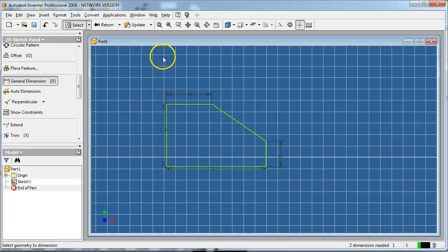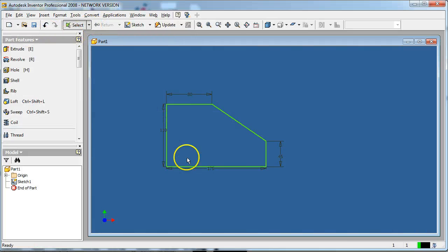So there's our shape. We're finished with the 2D profile. The 2D profile means that we've created the actual 2D sketch. It's just flat at this time. So we will get rid of the grid lines and we will switch our 2D into 3D, and we're going to take that profile and extrude it to give it the thickness or the dimensional appeal that we need.